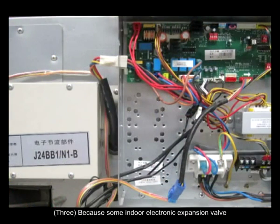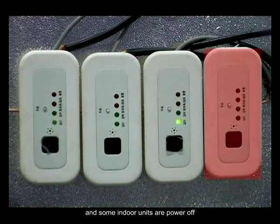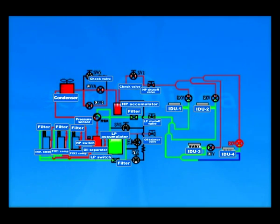3. Some indoor electronic expansion valve has a malfunction, or the indoor units are not on the same power supply and some indoor units are powered off. Then the refrigerant goes through the indoor units which are powered off or the electronic expansion valve that is stuck. It affects the system running performance.